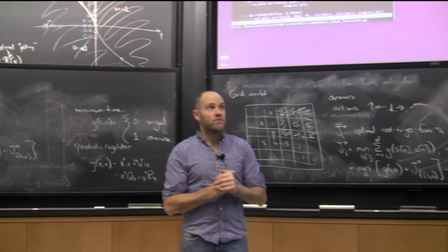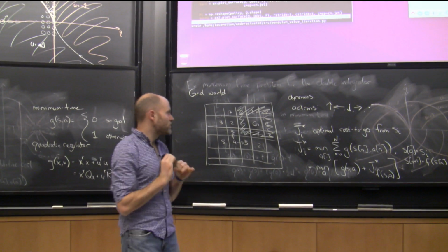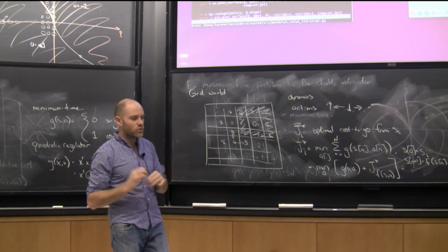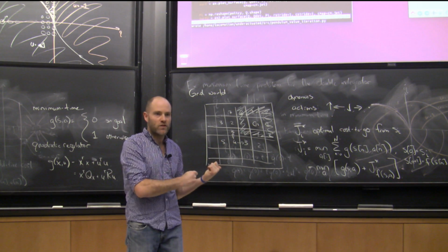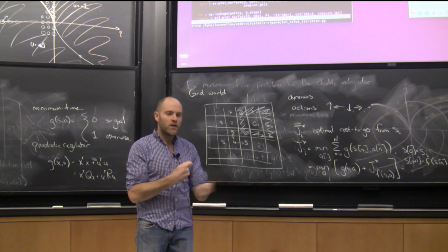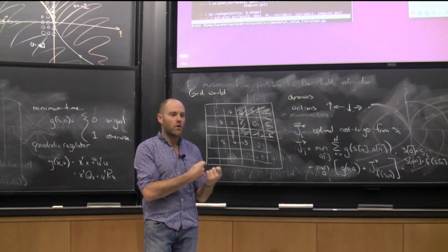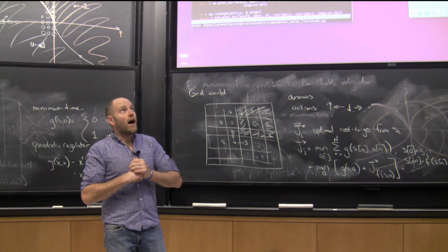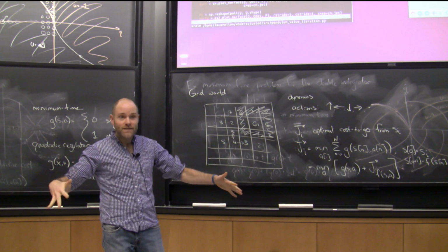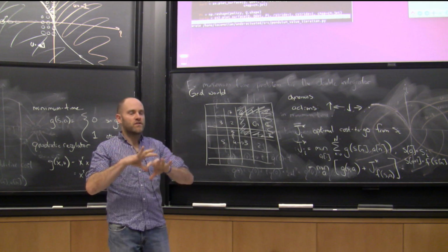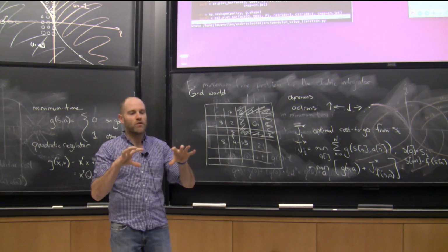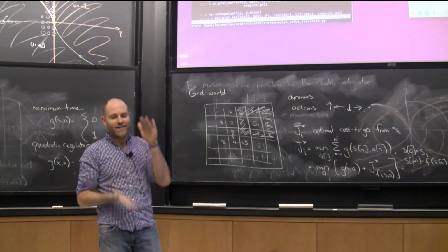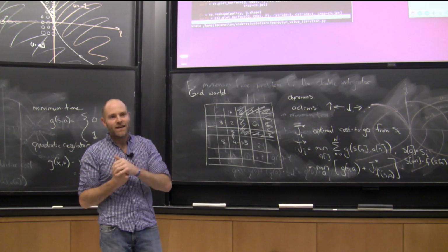The thing that almost everybody does, because these tools are so good, is you do state estimation to try to estimate your x, and then you run these controllers, and then you try to maybe do a couple things to make the controller robust to the fact that x might not be perfect. I actually think that's fundamentally wrong. Everybody knows that's not an optimal thing to do in the nonlinear context. But even the very notion of what is x, what is the dimension of my state, is in question.